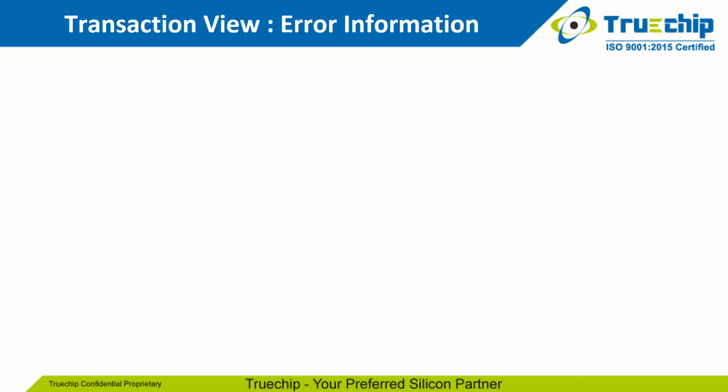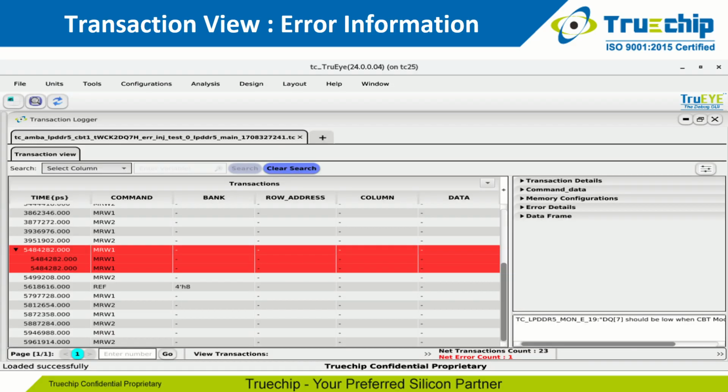Then comes the transaction view with error information. Like we have run a test and there comes a UVM error, and we have to see at what time and what error has occurred. So this representation will show each and every piece of information regarding that error with its expected and actual value, meaning what was the expected value as per the specification and what value has been received by the monitor, at what time scale and on which command, with multiple more fields as per the error, which play a vital role in debugging easily.